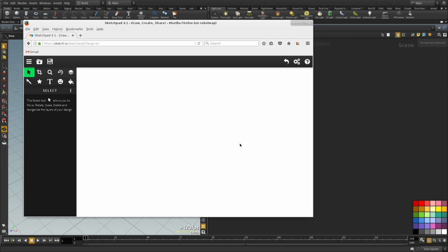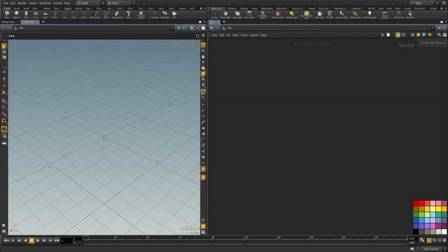The other thing that I didn't explain is converting existing geometry into volume. Now, Houdini has two types of volumes. There is VDB volume and the Houdini native volume. The main difference is VDB is much more efficient, much more optimized. We can push the quality a lot more, and the memory will still be reasonable. With the Houdini native format, the data is going to be much heavier and much slower. And so we're going to be using VDB, which is what Side Effects encourages everyone to use.